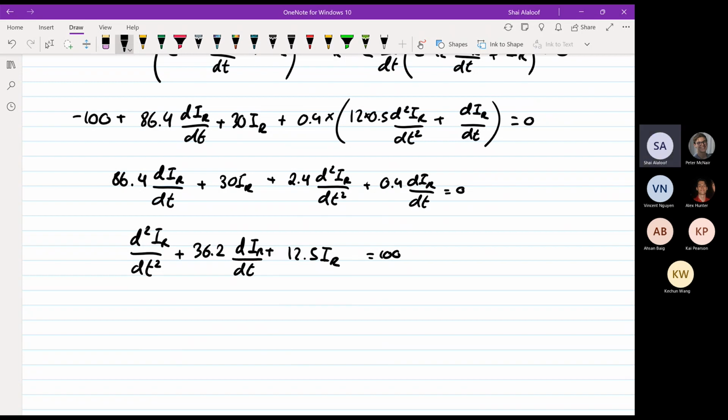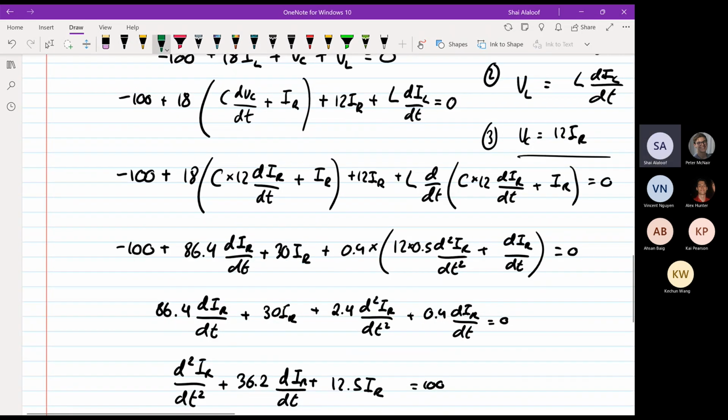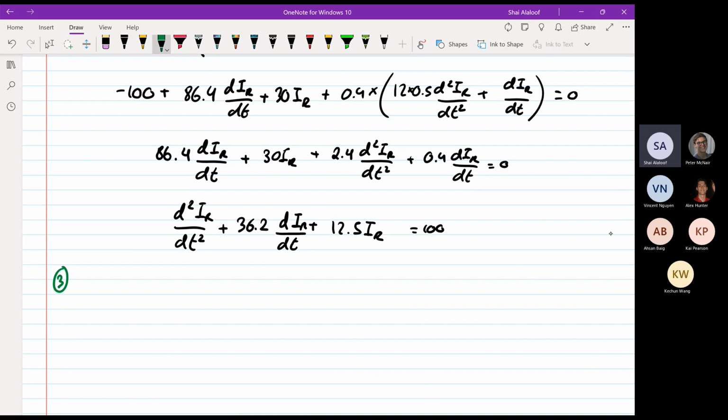All we have to do is find what type of characteristic equation it is. So, what step am I up to? All right, 3. Type of solution. You can either have overdamped, underdamped, critically damped, or undamped. I think they usually like to give either overdamped or underdamped. I don't think you'll deal too much with the critically damped cases, but since it's open book, you might as well have a formula sheet with all of the damping cases.